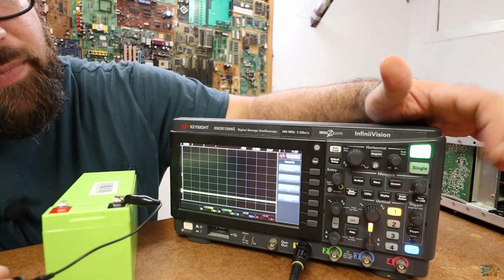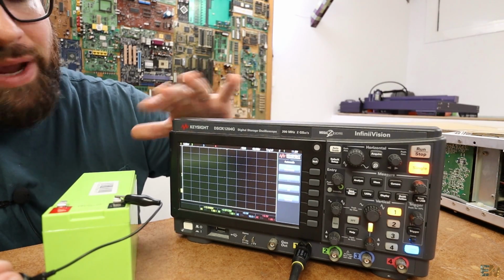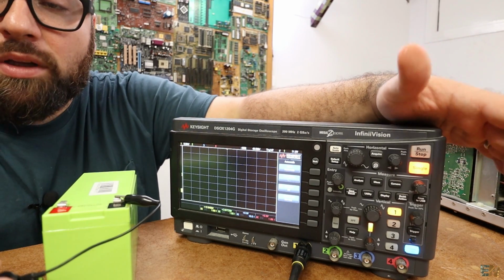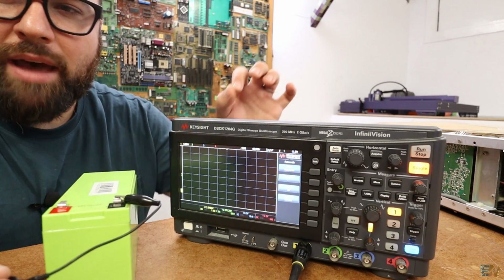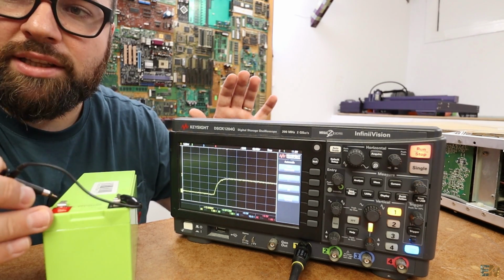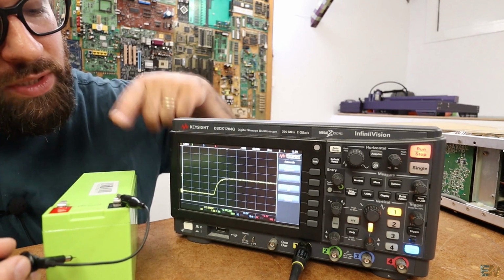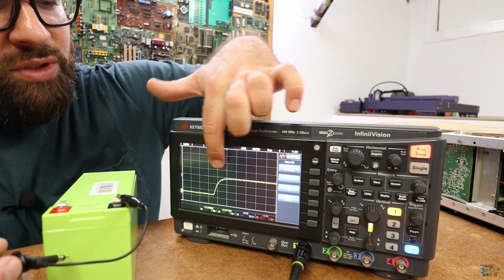But then we have the single button. If I press this one, it won't show anything on the screen, and it will wait till the settings for your trigger will be completed. So for example, if you're waiting for a specific signal to happen, at that exact same moment, if I touch it, as you can see, it made the trigger just one snapshot, and it will show me on the screen. As you can see how the voltage is charging from 0 to the voltage of the battery.